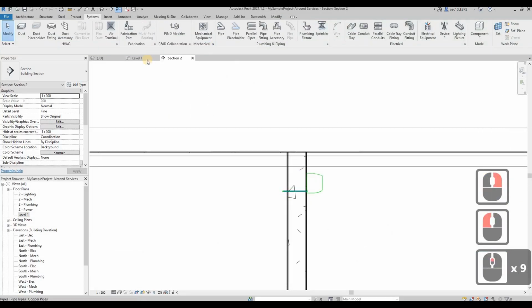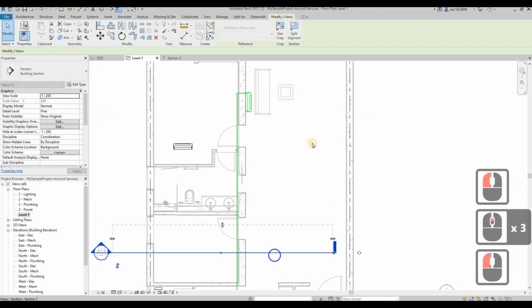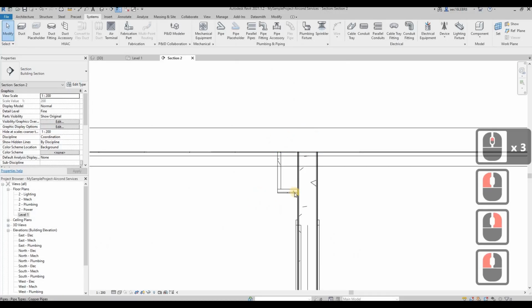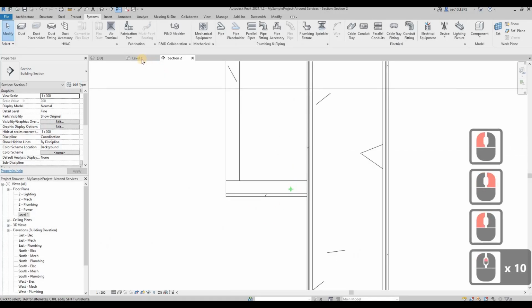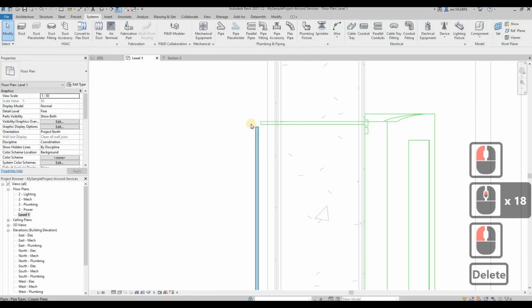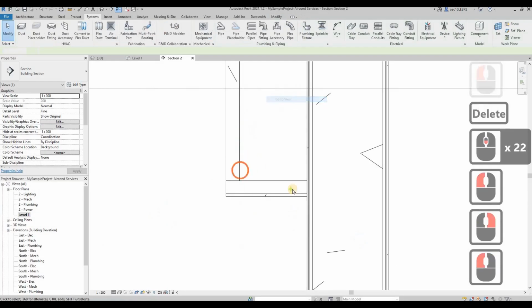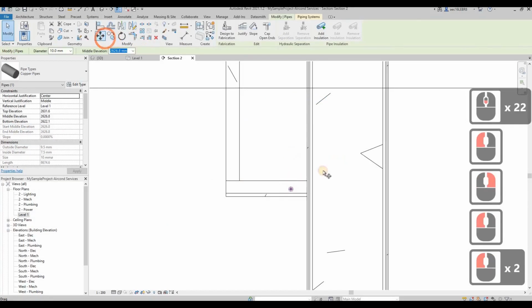This is your copper piping. Then just check here, then go to view. This pipe is under the ceiling box up. Then you need to raise up your copper piping here to at least a height inside the ceiling box up. Okay, go up.